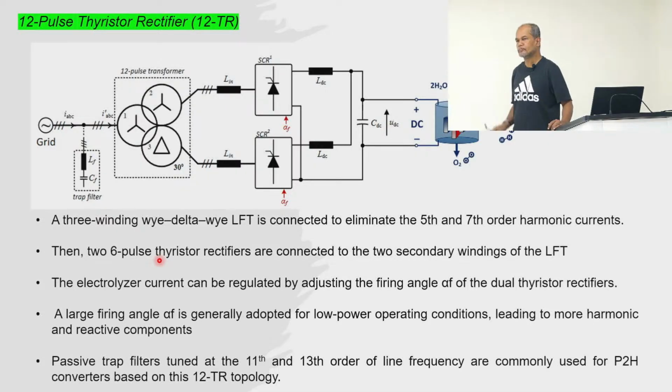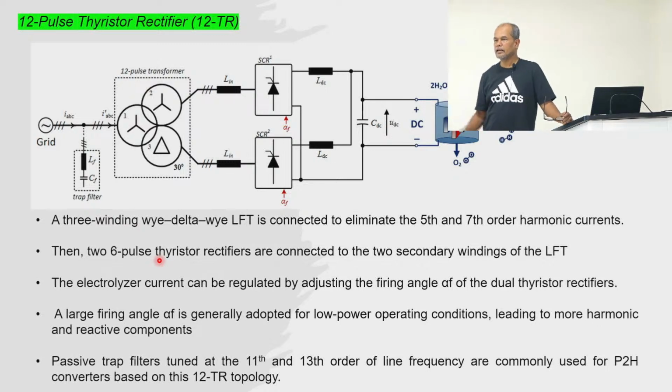They already have a big electrolyzer, and they are actually using 24 pulse, not 12 pulse. But mostly 12 or 24 pulse rectifiers are used for electrolyzer applications. Any of the rectifiers could be thyristor, IGBT, and also sometimes diode as well, right?